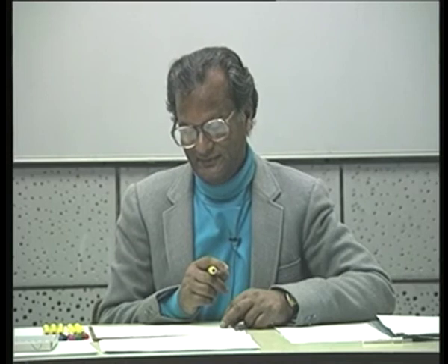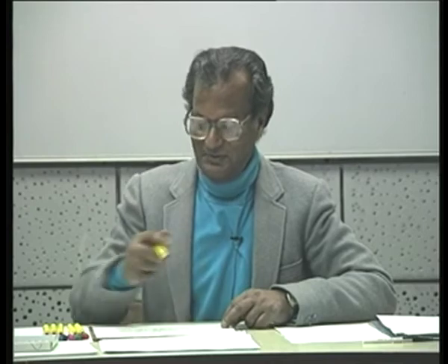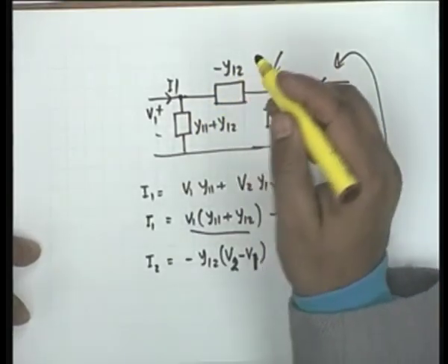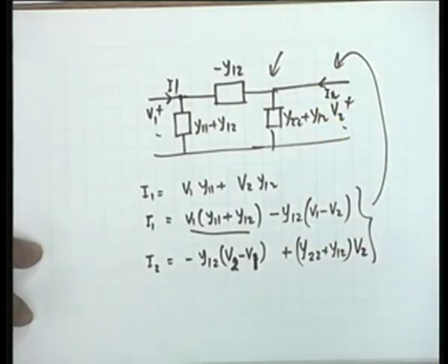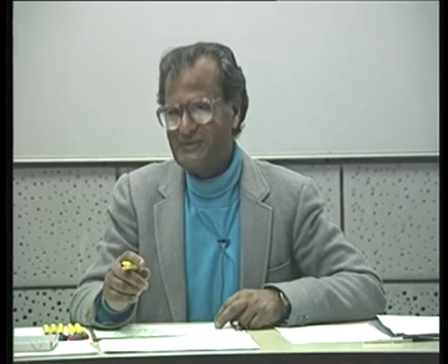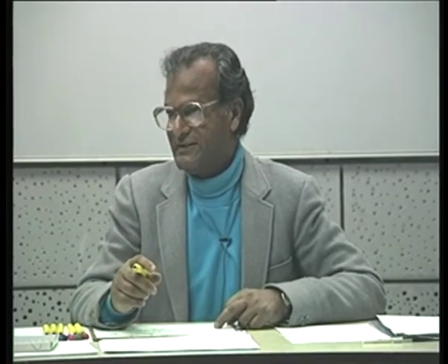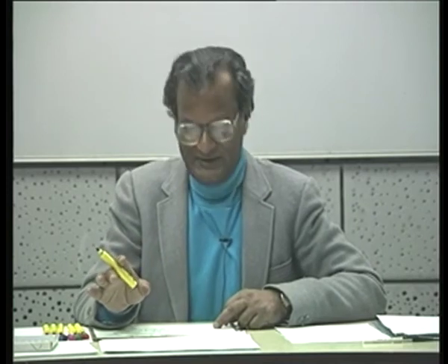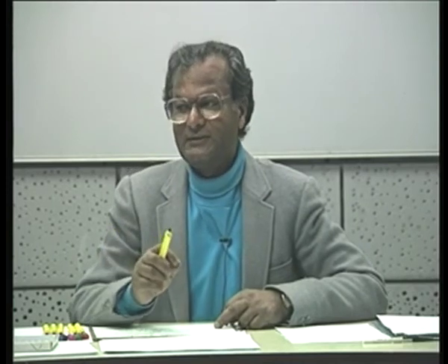That's right. So what's the physical significance of a negative impedance? It may not be negative. Y12 itself may be negative. There is no physical significance of a negative impedance other than that it's negative. It is possible to get negative resistance, negative inductance, negative capacity, no problem. Not with coils and parallel plates, we have to use active devices.